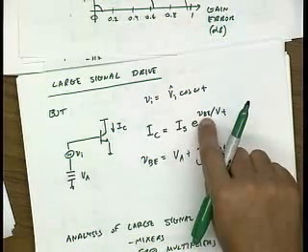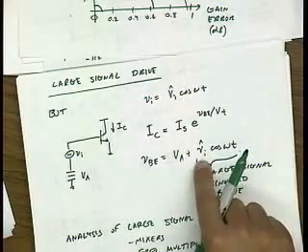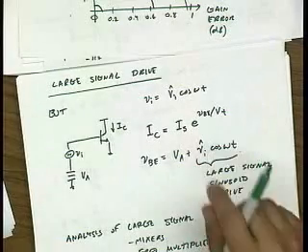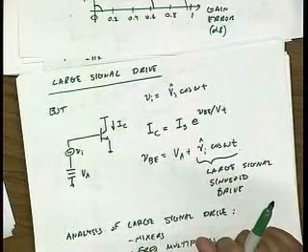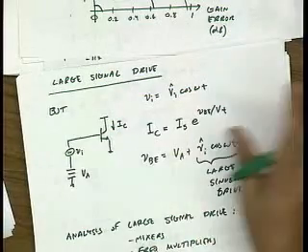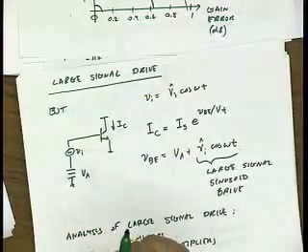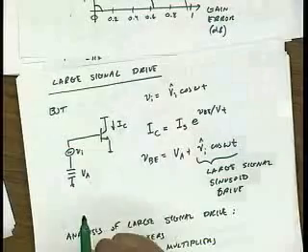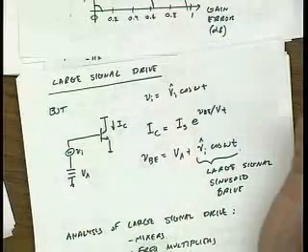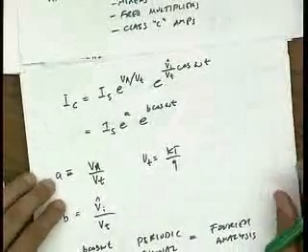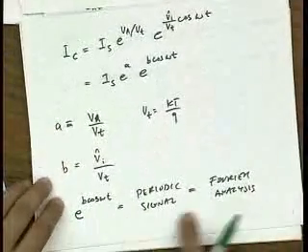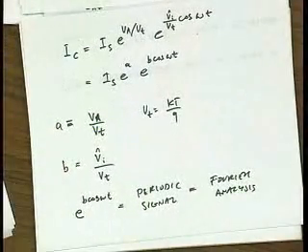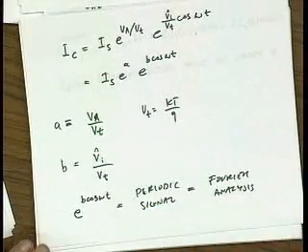So the signal component, V input, should be smaller than Vt, roughly, to make this power series valid. Now I want to make V input arbitrary. I want to make it a volt, let's say. And I don't want to do power series with 100 terms. So instead, I just say, I get what I get. At the end of the day, I'm just going to take its Fourier transform and look at what frequency components come. Because it's periodic, I get a Fourier series.